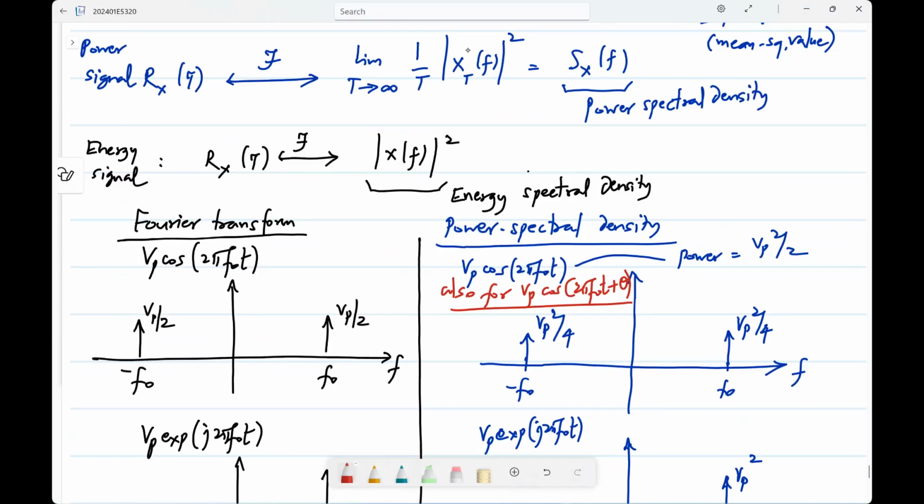It's called the one-sided power spectral density. Now there is no way we can go back and change in time. If everybody used only one notation, it would be easy, but that's not the case. Usually in communications, two-sided stuff is very common, and in circuits, one-sided stuff is very common in some areas. Those of you taking advanced electrical networks may find the two-sided stuff easier, because you have frequency conversion and so on.